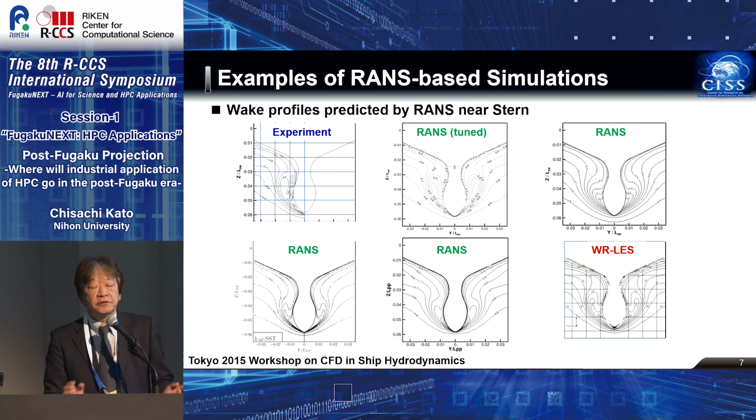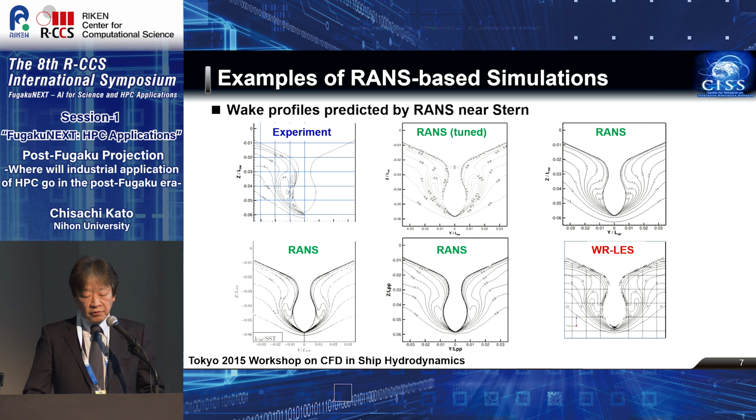So instead of relying on the turbulence model, we have been trying to resolve everything we need to, down to very tiny edges, like 500 micrometers around the 7-meter long ship.